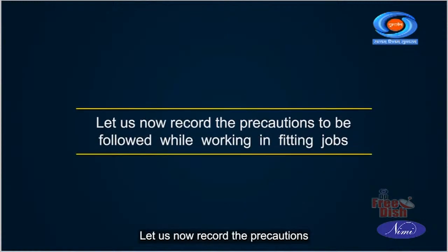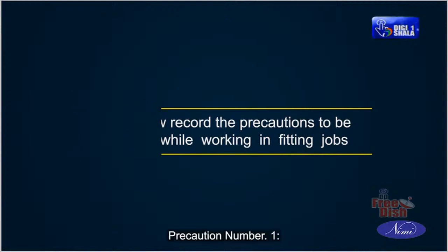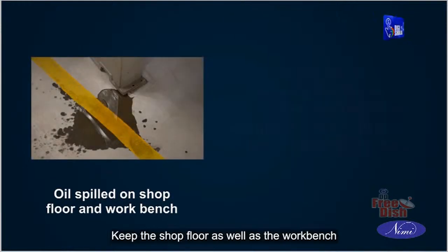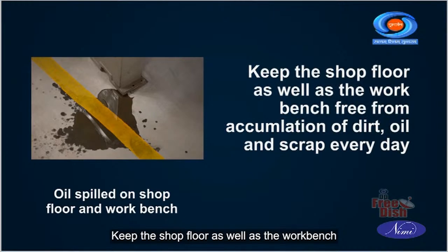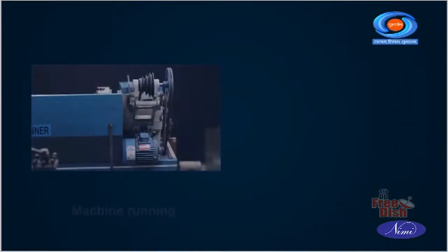Let us now record the precautions to be followed while working in fitting jobs. Precaution number 1. Keep the shop floor as well as the workbench free from accumulation of dirt, oil and scrap every day. Precaution number 2.